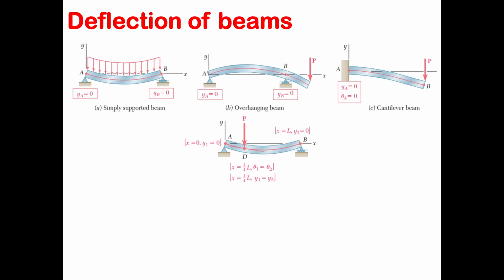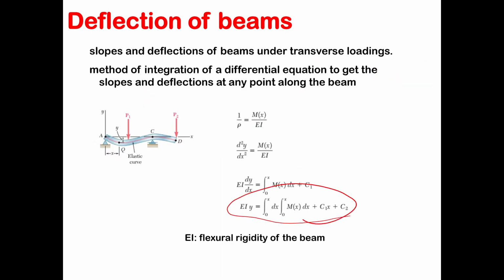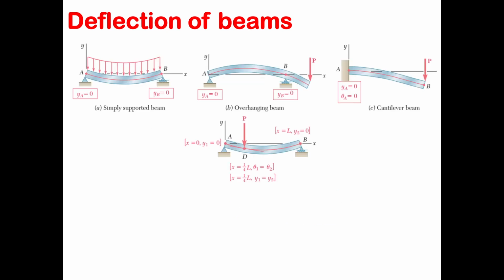So this equation here is called the equation of the elastic curve, and this is what you want to have for your experiment, right? To be able to determine that, because you have already measured the loads, you can calculate the moments, right? When you have the equation, you can essentially relate the deflection and load.